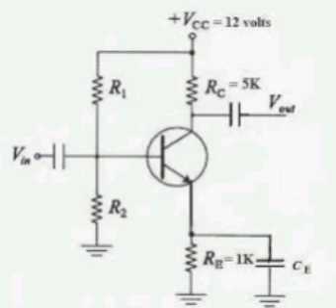When pressure coil has inductance where tan beta equal to omega LP by RP, developed torque TD is directly proportional to IP IC cos alpha dM by d theta.